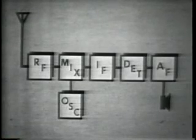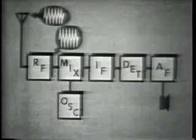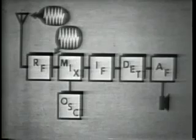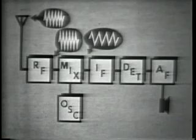But will a conventional receiver receive this different kind of signal? Let's look at a typical AM receiver and see. The incoming sideband signal is RF. Now, RF amplifiers, of course, will receive this signal and amplify it, and it can be mixed to produce an IF signal. The IF signal will be amplified as usual.